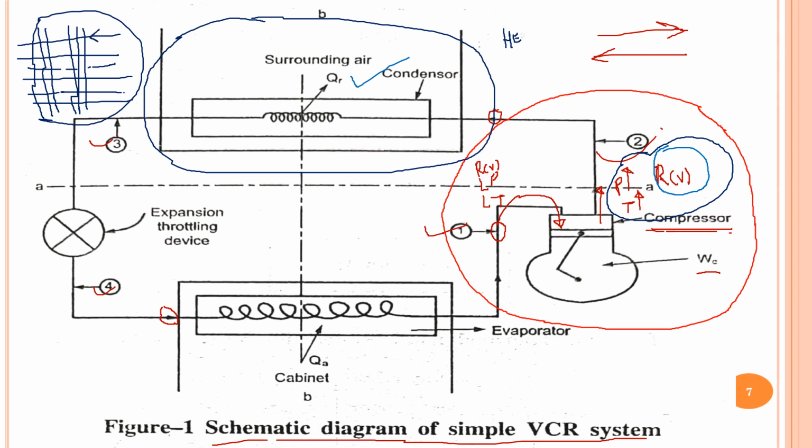So in this condenser tubes, high pressure, high temperature refrigerant is entering. And as we know that this condenser is kept away from the wall. You can say this is a wall of your house, wall of the room. And this is a condenser. So here the distance is observed where air is between the wall and the condenser. So air is a cold fluid, your refrigerant is a hot fluid. So this refrigerant will reject the heat. This is QR. Heat is rejected by the refrigerant.